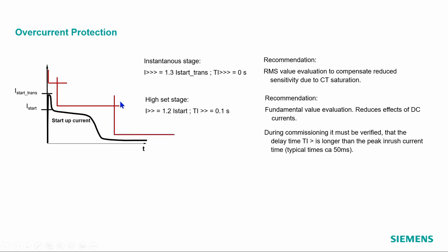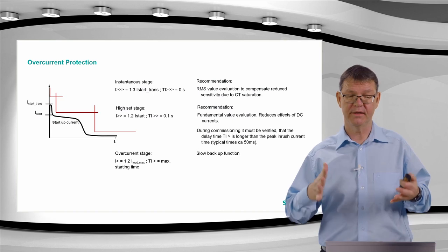Okay, and finally the relatively slow backup stage, if at all we can apply such a thing, then we need to be higher than the maximum load current. Okay, that's how we can apply the overcurrent protection.